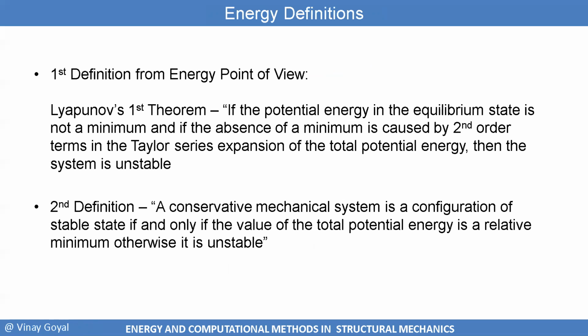The first definition from the energy point of view is Lyapunov's first theorem. If the potential energy in the equilibrium state is not a minimum, and if the absence of a minimum is caused by second order terms in the Taylor series expansion of the total potential energy, then the system is unstable. I'll repeat again, if the potential energy in equilibrium state is not a minimum,